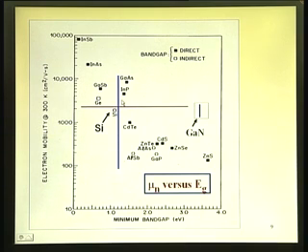So, among these materials, indium antimonide, indium arsenide, gallium antimonide, they are all direct band gap semiconductors, telling you that they could be used for optical applications, okay, dealing with light. But for microelectronics, they are no use because their band gap is much smaller than that of silicon. For example, indium antimonide is something like 0.18 or something like that. Indium arsenide is about 0.3 electron volts.